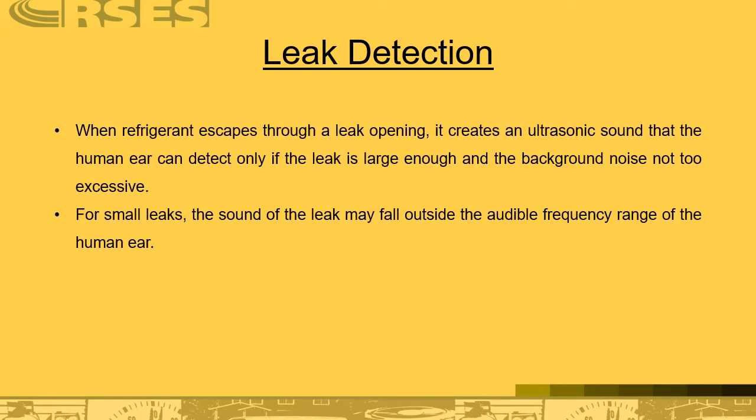When refrigerant escapes through a leak opening, it creates an ultrasonic sound to the human ear. It can only be detected if the leak is large enough and the background noise is not too excessive. For that reason alone, you have to wear earphones. With small leaks, the sound of a leak may fall outside of the audio frequency of the human ear. But I will tell you this, all the places I've used this leak detector, I've not had that issue. But if you have a lot of background noise, such as a machinery room, that's going to be a problem.